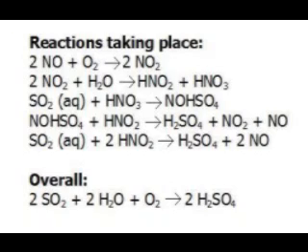The following reactions occur. Nitric oxide reacts with oxygen to form nitrogen dioxide. Nitrogen dioxide reacts with water to form nitrous acid and nitric acid. Sulfur dioxide reacts with nitric acid to form nitrous sulfuric acid. Nitrous sulfuric acid reacts with nitrous acid to form sulfuric acid, nitrogen dioxide, and nitric oxide. Sulfur dioxide reacts with nitrous acid to produce sulfuric acid and nitric oxide.